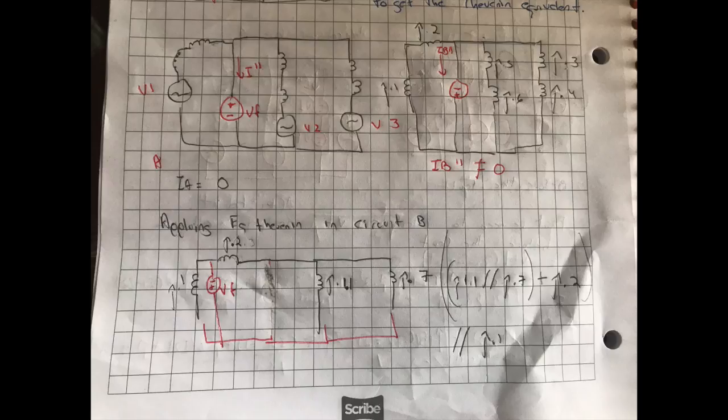So as we see, we get the real equivalent impedance, and with that real equivalent impedance, we calculate the current. The next step was to get each value of the impedances in the real value, not the per unit value. That is because in the simulation we are going to use it.